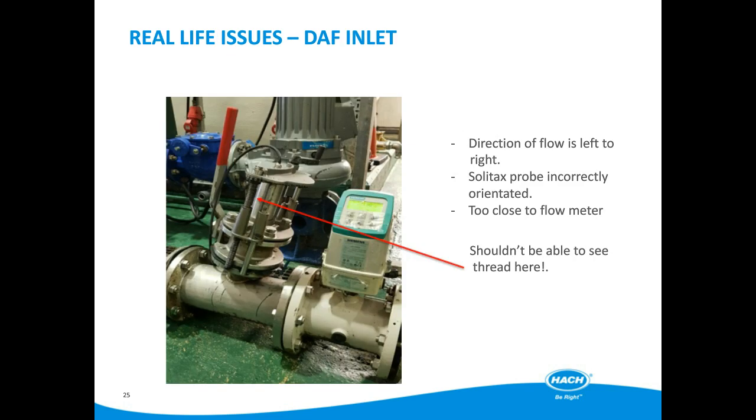In this slide, and the one following, I'll just go through some issues that we see. This picture shows an installation by an unknown contractor. The plant operator complained that the solids probe had never worked, and it's quite easy to see why. Although the Solitax probe has been installed facing the flow, which is recommended, there are several issues here.